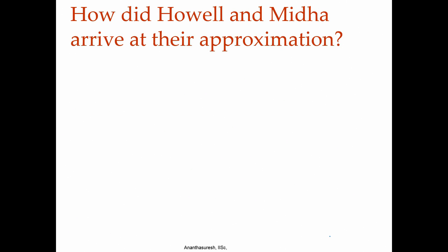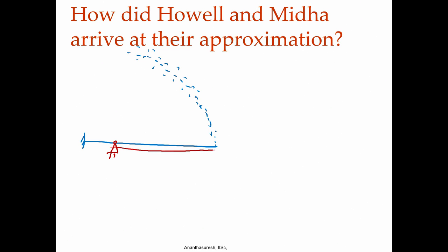And this kappa. What they did was, when they get this spread of data, that is, if I take a cantilever beam, it is going to give some points like this, and we have seen that in the earlier slides. So now the first thing they did was approximate this with a rigid body crank, of length, in their notation, gamma times L, where gamma is a characteristic factor.